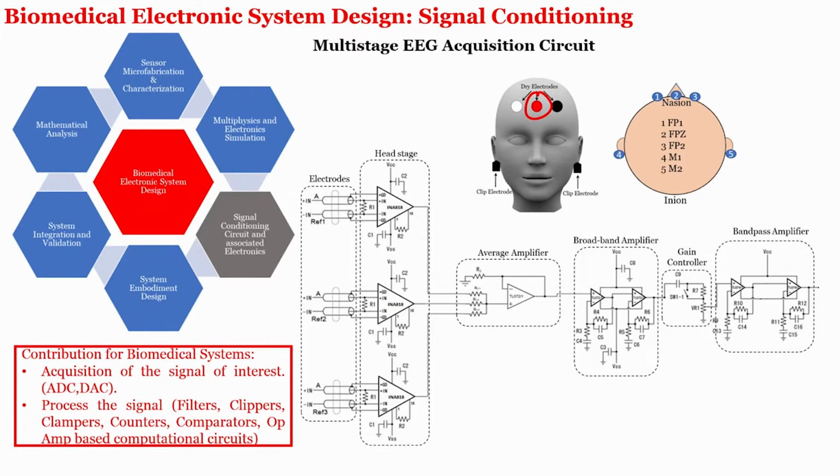For certain applications like neonatal screening and hearing screening, if you apply a given signal, which can be your ABR, you will be able to see the EEG signals from the frontal electrodes. So, another technique for measuring the EEG under different audio stimulation is ABR, another one is AEP, another one is mismatch negativity, another one is the positive peak at 300 milliseconds. So, there are several different parameters that one can use for designing this audio stimulation.